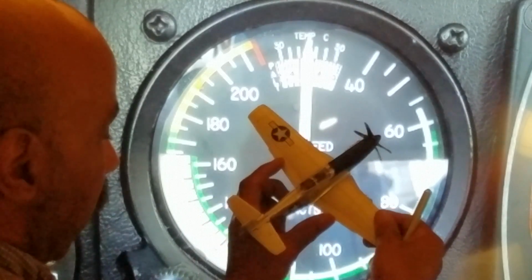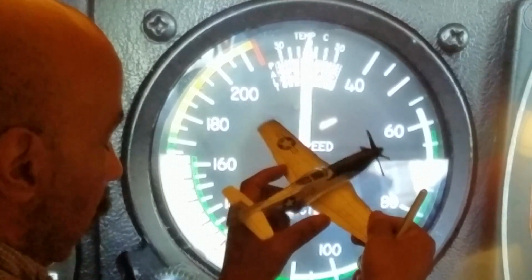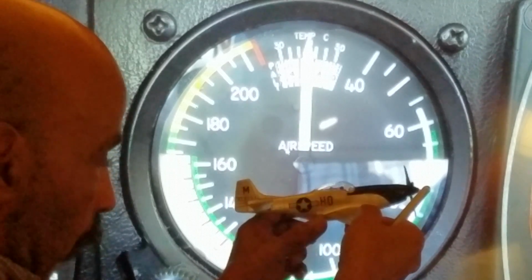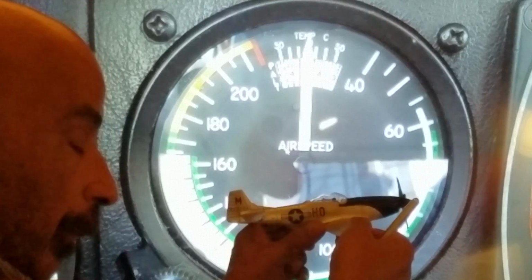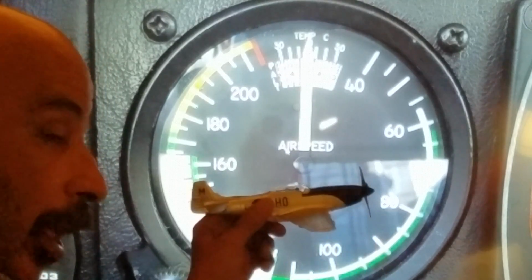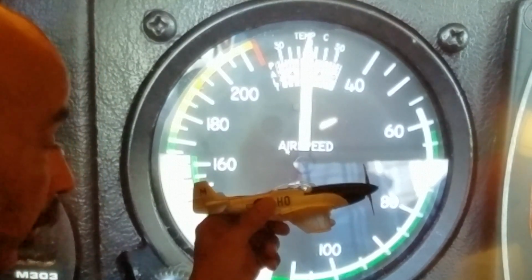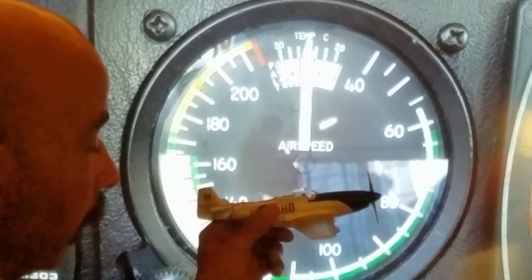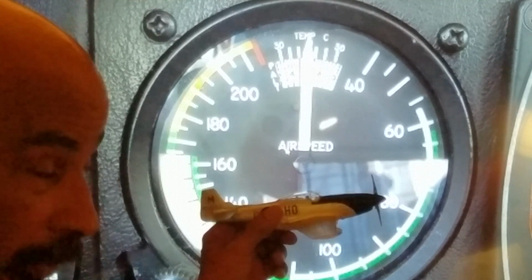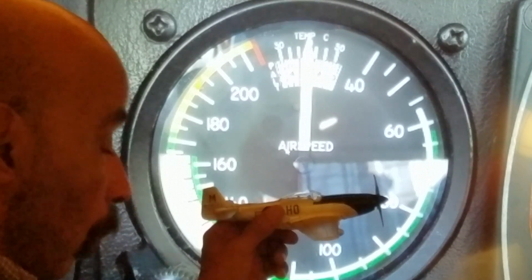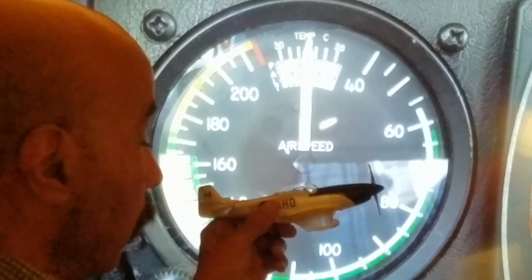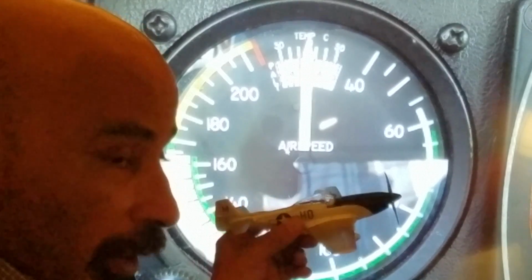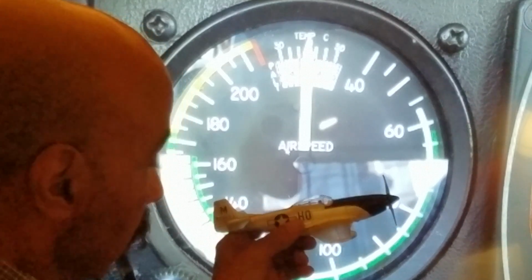Again, these are the flaps. They come down together. Takeoff flaps is usually less than 20 degrees of flap extension. It adds a lot of lift to the aircraft so it can take off at a shorter takeoff roll distance than if all flaps were retracted. You can take off with flaps fully retracted, or you can take off with flaps extended to a takeoff position.